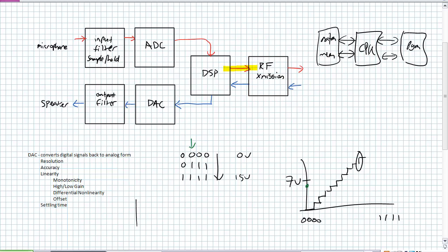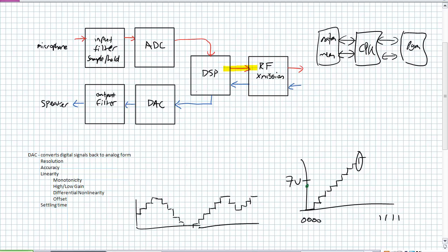If you're going to reconstruct, here's the actual output of your digital to analog converter. So this is our actual output. That is what the digital code is outputting, that stair stepped. What we're going to do is put it into our reconstruction filter, and it's going to give us that smoothly varying analog signal, very similar to perhaps what was coming in, our desired effects. Okay, notice the difference between the green and the black there. There's none of that stair step in there. It's giving that nice, desirable analog signal.